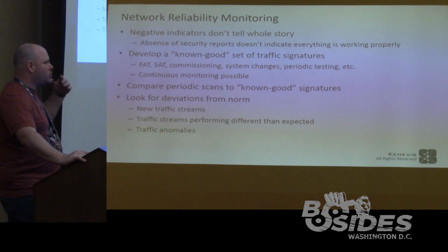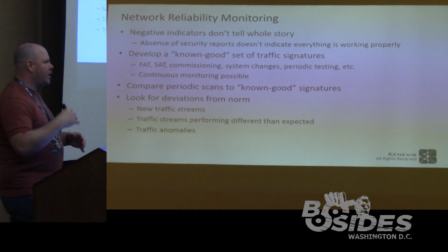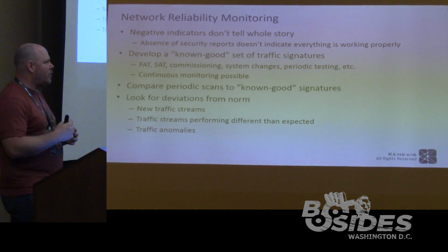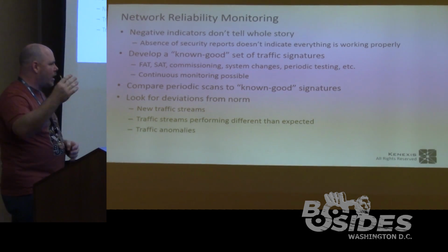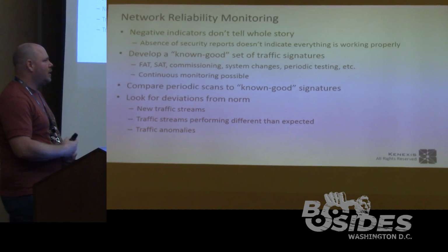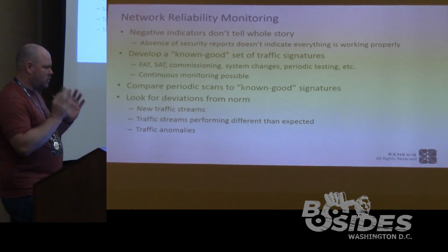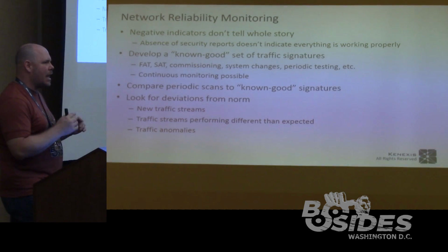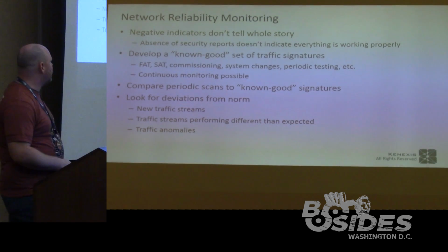These systems don't change all the time. You shouldn't have people down on the control networks looking at web pages. They shouldn't be going out to, name your malicious actor country. They shouldn't go out to those countries. If you start seeing traffic going there, there's probably something wrong. Egress filtering for firewalls is one of the biggest things that should throw up red flags. If you start seeing egress traffic out of your company from the industrial control system directly, then you should be running to figure out what's going on.